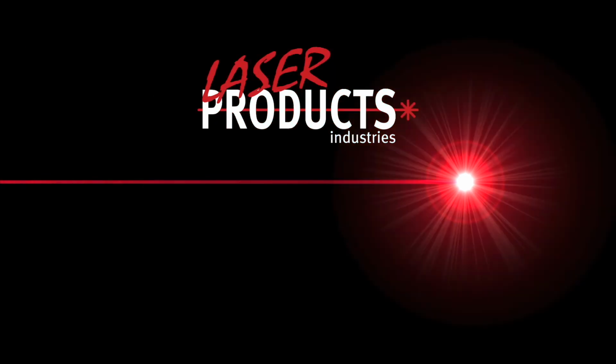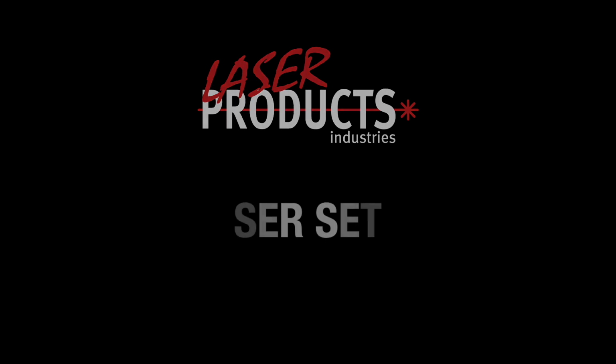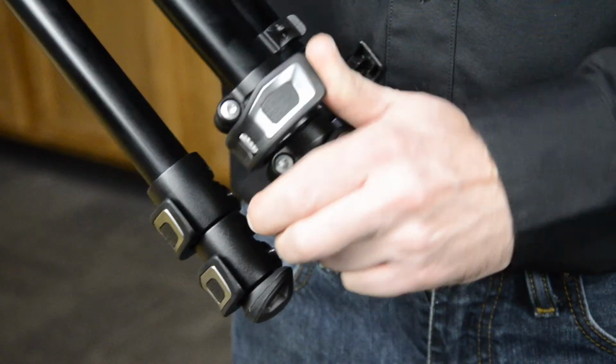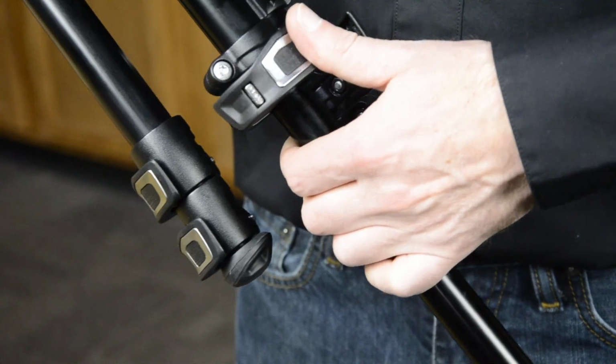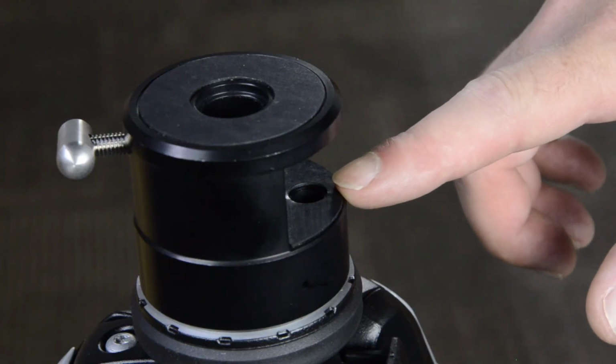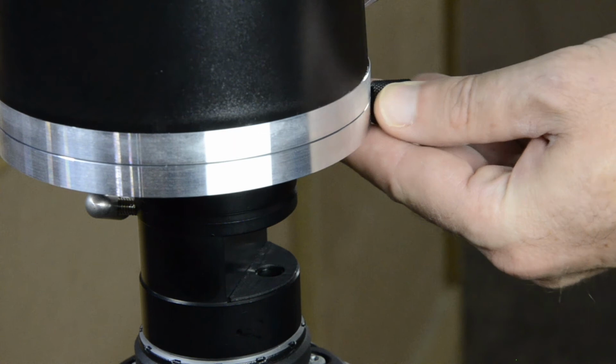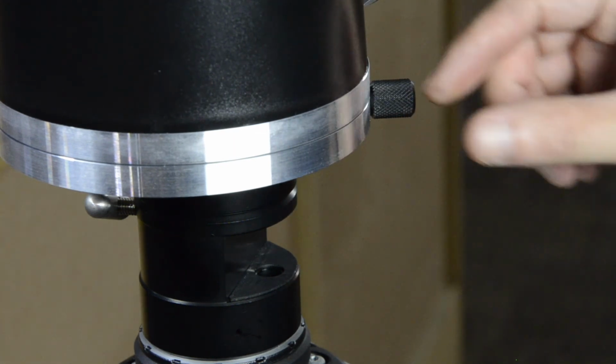In this video, we will be covering the proper way to set up your 2D, 3D laser templator for measuring a countertop. Unclamp the upper legs of the tripod, as this is the ideal height for most countertops. Make sure the peg hole is facing you. Place the 2D, 3D on the tripod and rotate the lower micro adjust knob to your dominant hand side.